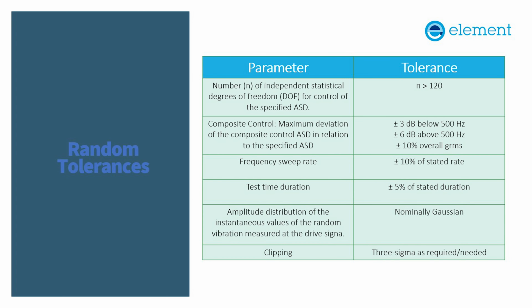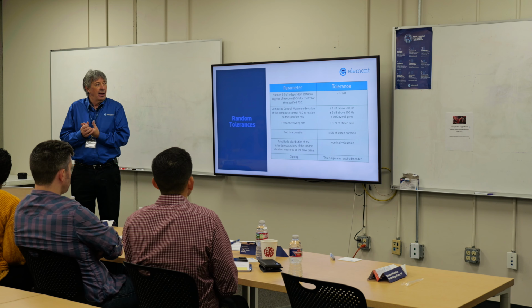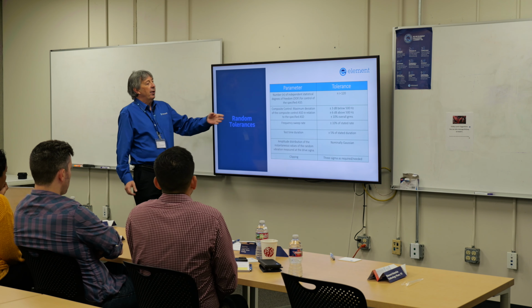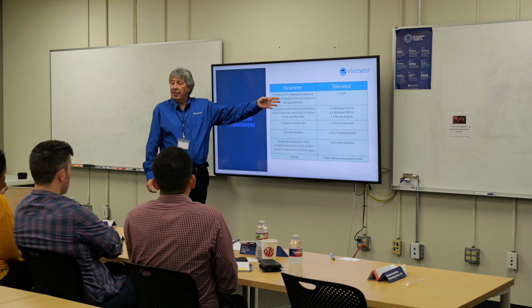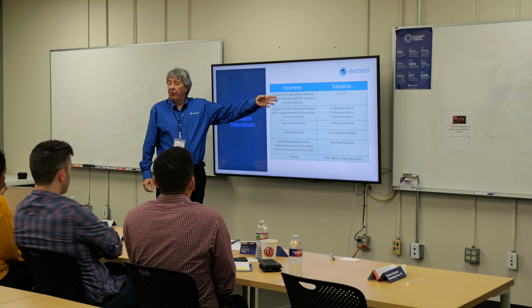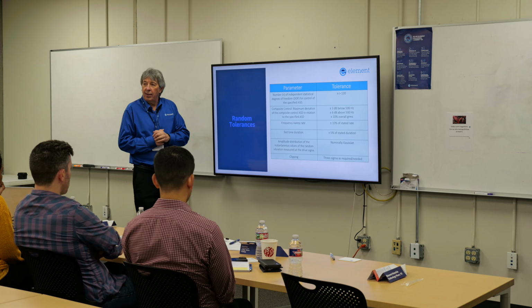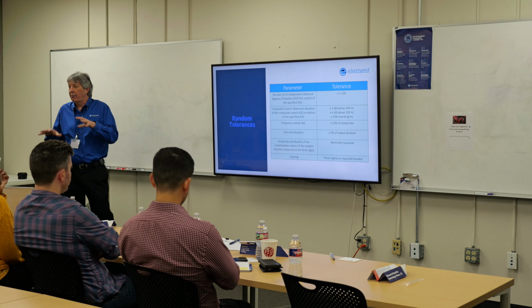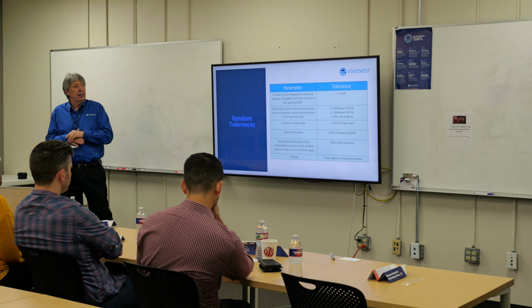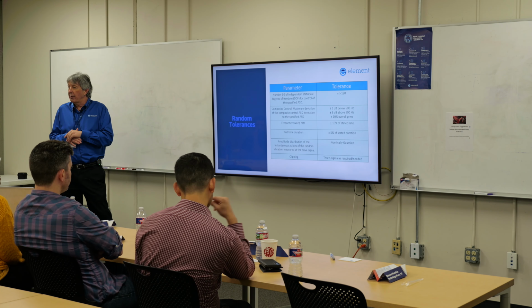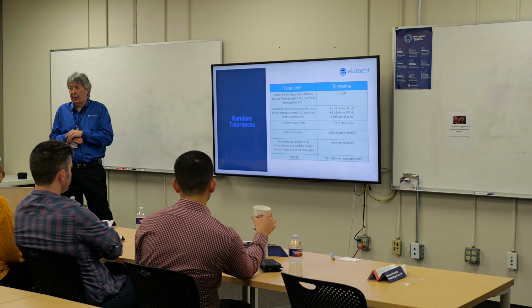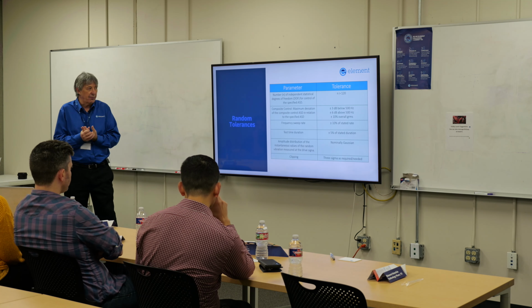If you're at 120 degrees of freedom, we're 94% sure what the table's doing, so pretty good accuracy. The higher you bring the degrees of freedom, the more accuracy you get, but now you're throwing away loop time. It takes longer, you need more loops. So 120 seems to be the perfect mixture. That's what degrees of freedom is, it lets us know the accuracy of our random vibration.